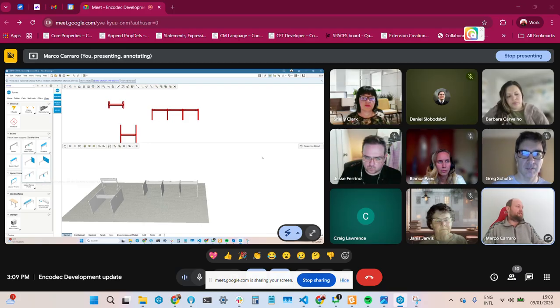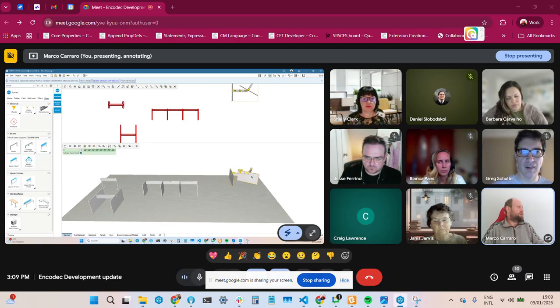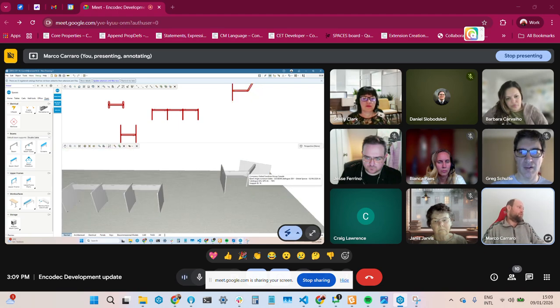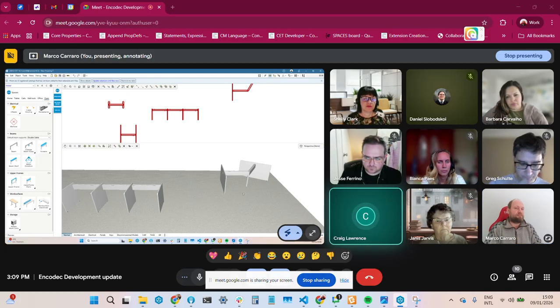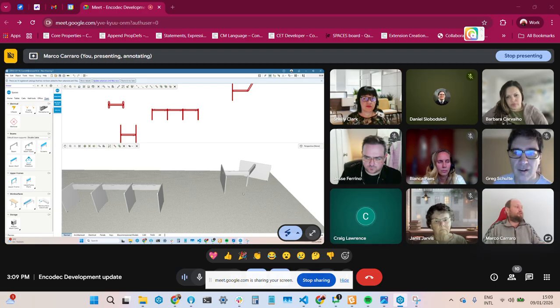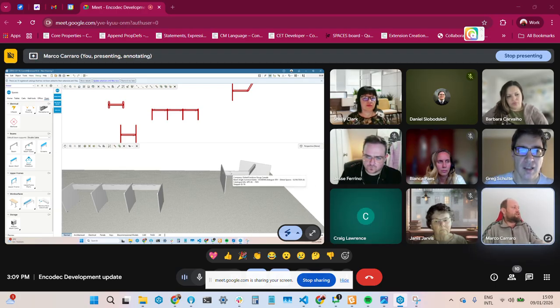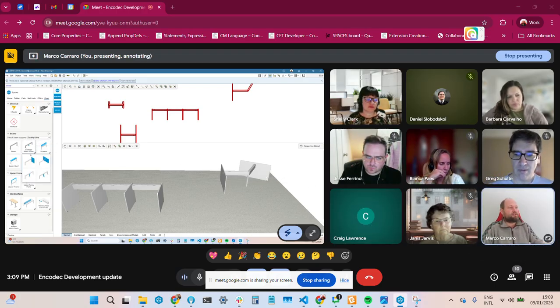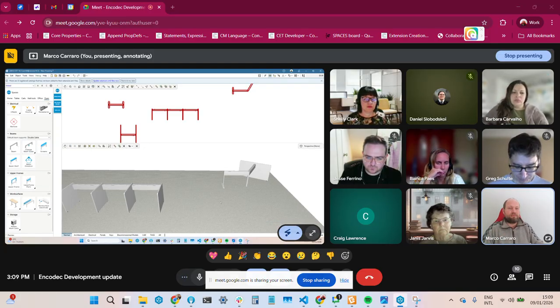For example, in this case, I will not be able to place a double gable in here, but I can have them as a double gable as default. So it's just a default setting. It doesn't mean that they can't change it. No, absolutely. I used here a double gable as a default, but I can change a single one without any problem, so far as it's possible.